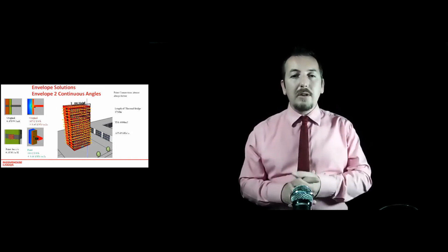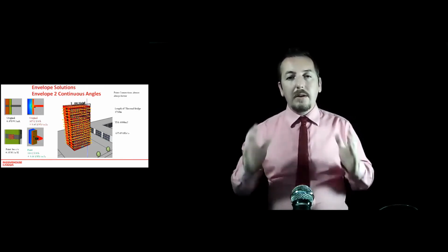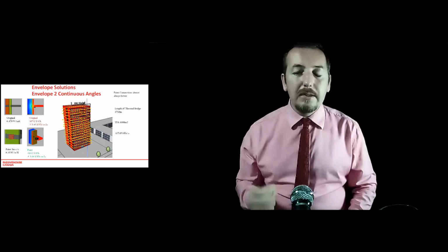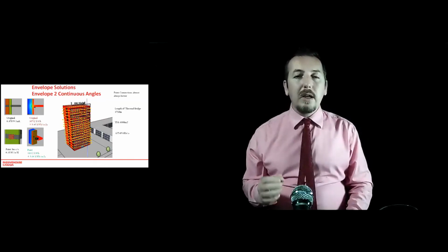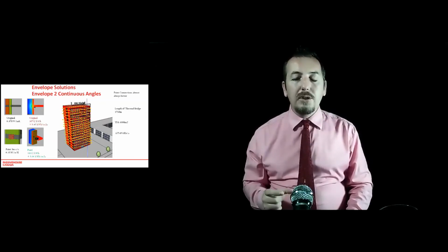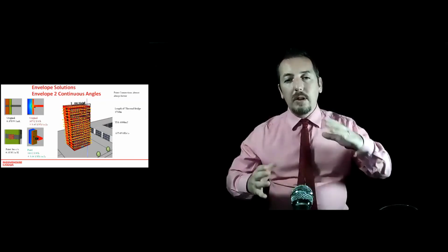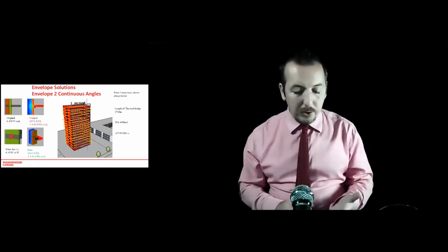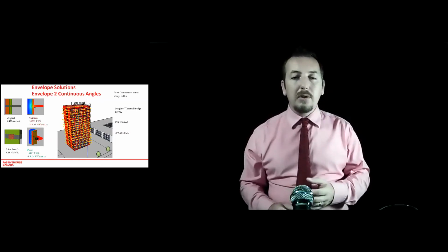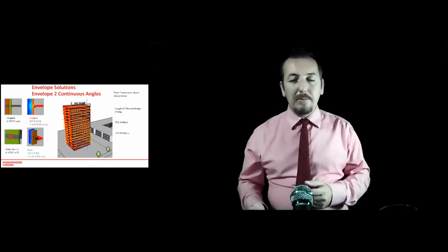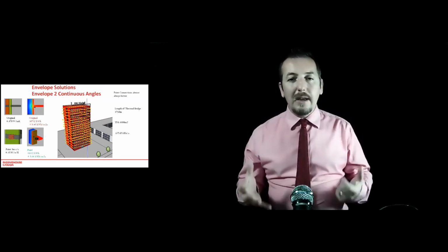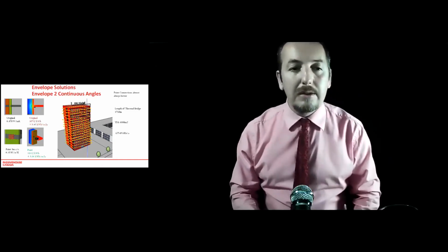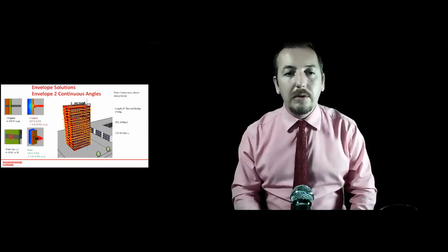Now, just imagine if you had intermediate walls that broke your insulation layer. It's a very similar effect. And this is why I'm saying you have to constantly focus not just on the psi value, but on the magnitude of the psi value and how long a length it's going to occur for, what the size of your building is. And having tools like Design Passive House, the SketchUp plugin and PHPP, and this mold simulator and the thermal bridging course that we're doing enable you to not guess it, but get it right every single time and not have to rely on someone like me who does the thermal bridging consultancy.